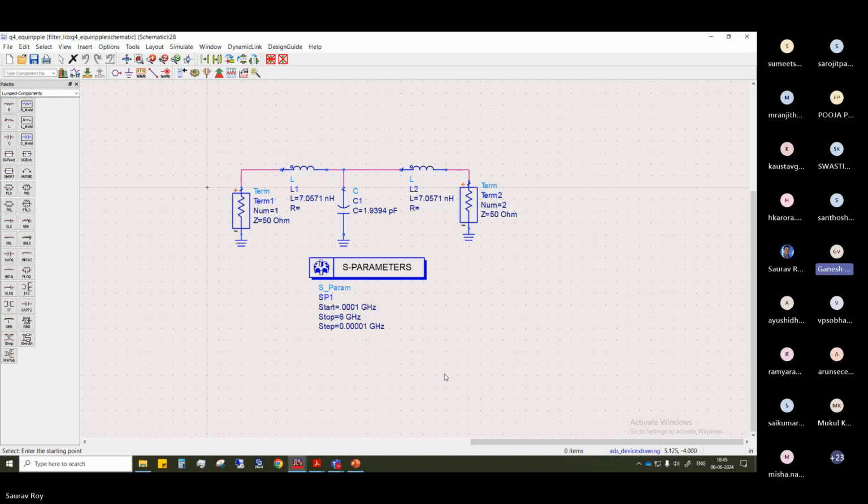I just want to know whether it's a mistake or whether in the capacitor the positive is being grounded. No. See, these are all AC, right? RF means AC. So there it will not matter. You have to always follow basic circuit things. So it's in AC, so it doesn't matter, right? Yeah, it does not matter because plus and minus are changing.